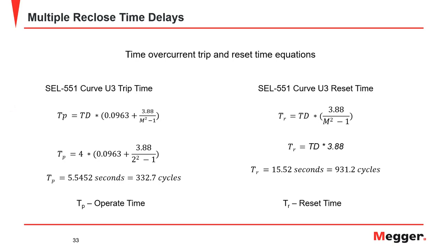All right, thank you. Question from Mike. What is a fuse dropout? In short, that's when a fuse maybe has been damaged. There's no good reason for it to blow at that particular time, but because of previous accumulated damage, it just fails and opens up. I mean, it's kind of a simple situation.